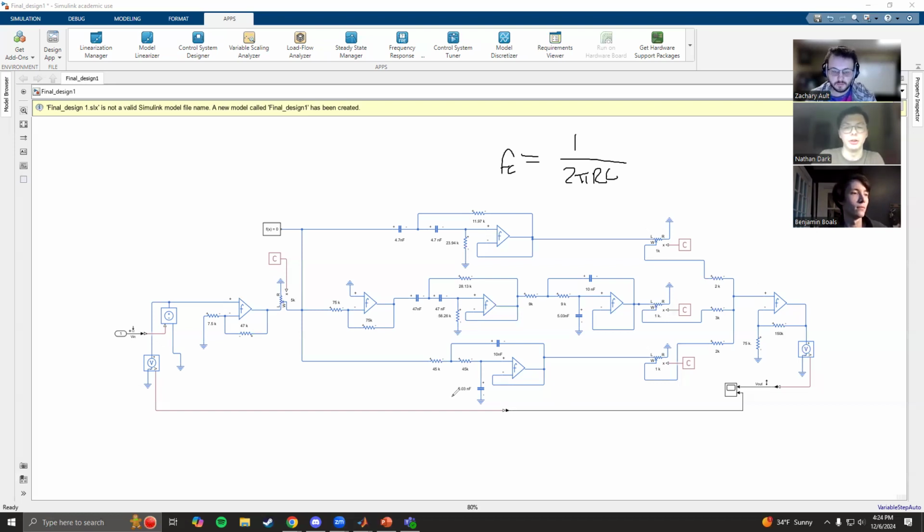So then after the bandpass below it, you have the low pass filter, which is designed the same way as the high pass, but you'll notice it's just reversed and it uses the same equation as the first one. And it blocks out any frequency above 500. And all the filters then lead into the potentiometers, which control how much voltage is then pushed into the adder circuit, and it just does that by changing the resistance.